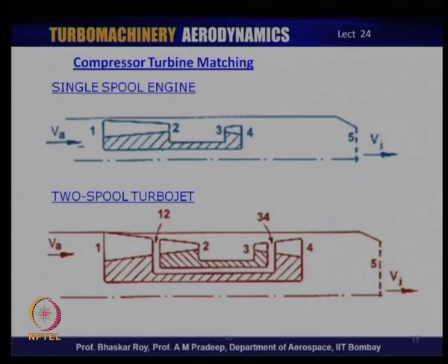One of the things which I mentioned is you need to do compressor turbine matching, and so this is just a very quick block diagram of the matching. If you have a single spool, you have to match this compressor with this turbine. If you have a two spool engine, you have to match this compressor with this turbine, and then the HP compressor